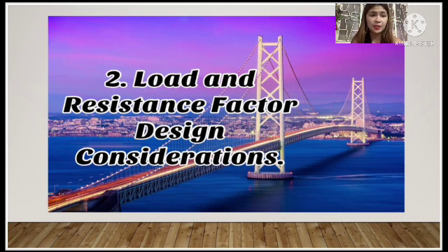So the transverse reinforcement in the pier column should meet the minimum requirements of AASHTO LRFD 5.7.4.6 to ensure that sufficient confinement is provided for the concrete. In seismic zone 2 and higher areas, additional transverse reinforcement is required to enhance the column's ductility.